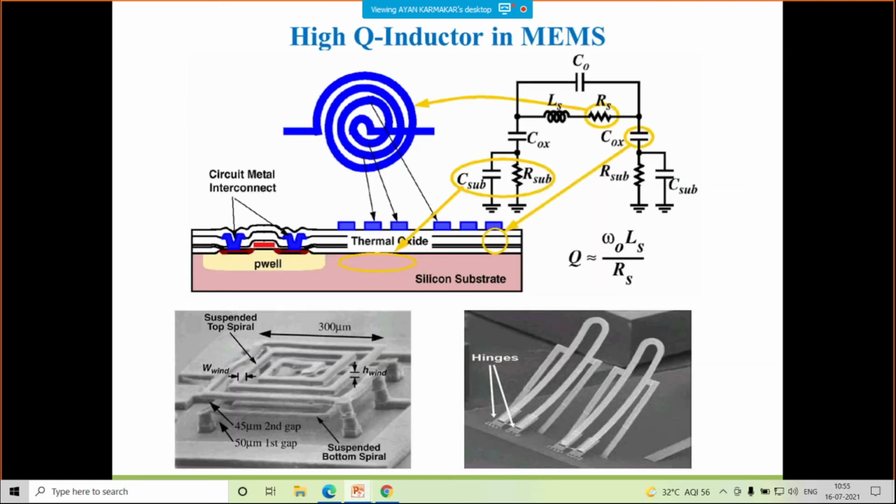Now, this silicon RF technology is best for the implementation of the LNA and different components also. For that, one of the very basic components is the inductor. This inductor is really very essential for any RF engineer, which is not normally available with CMOS circuitry, because in CMOS you can make an inductor now, but you cannot make a high Q inductor.